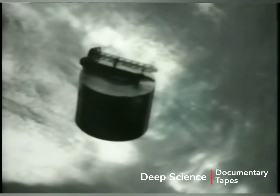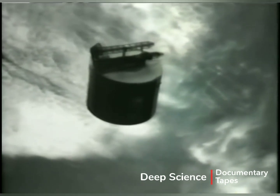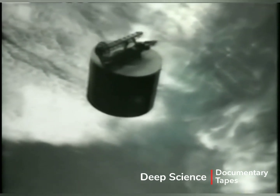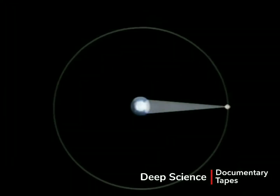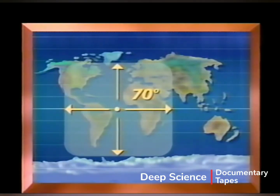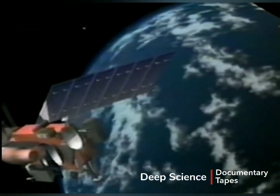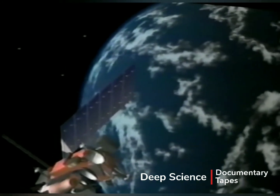Such orbits are called geosynchronous and are used to provide a continuous communications capability among any system of ground stations within their field of view. The geosynchronous orbit field of view is constant and is limited to a latitude zone of about 70 degrees north and south of the equator. Effective satellite communications from geosynchronous orbit is not possible at either pole. However, because of their altitude, their field of view covers nearly half the globe.